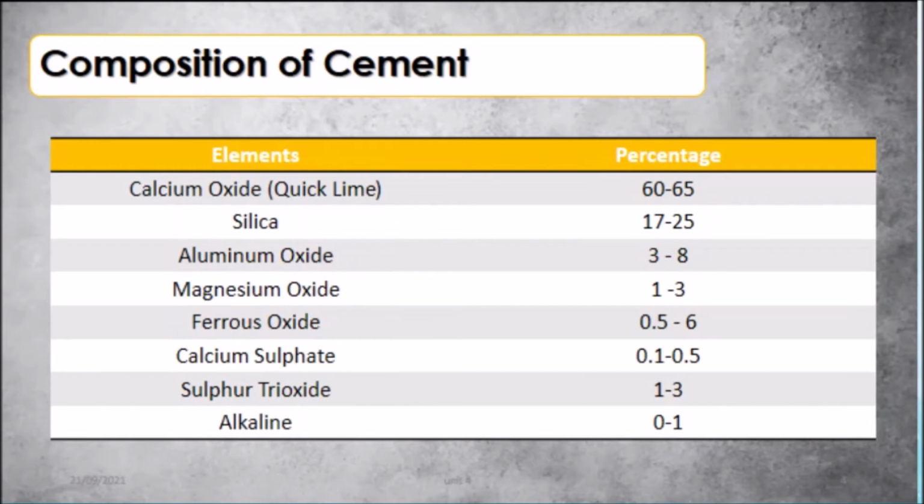Almost every construction work requires cement. Therefore, the composition or ingredients of cement is a matter of great interest for engineers. Each ingredient has different functions. By altering the amount of an ingredient during cement production, one can achieve a desired cement quality. For instance, the lime. Deficiency in lime reduces the strength of cement. Also, it causes cement to set quickly.